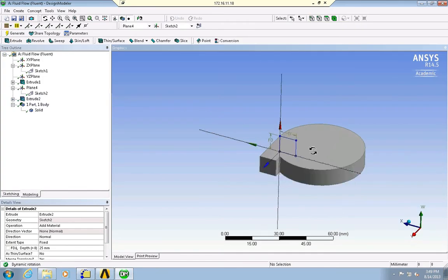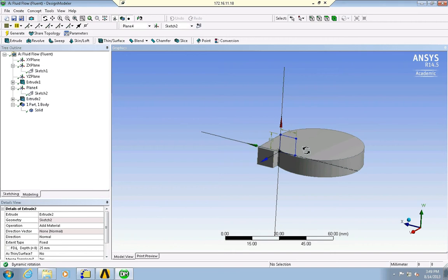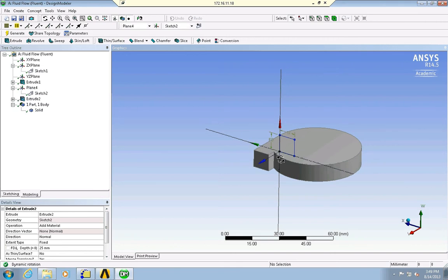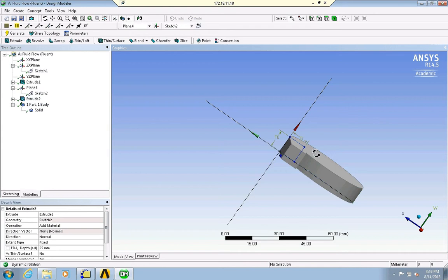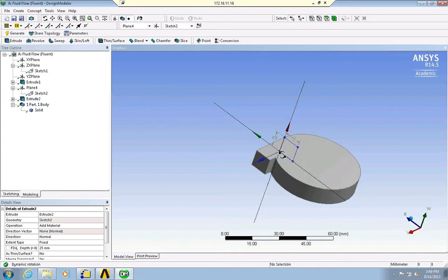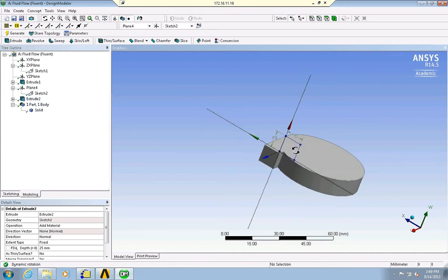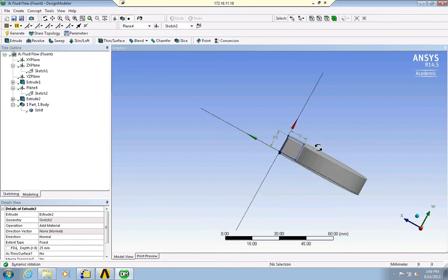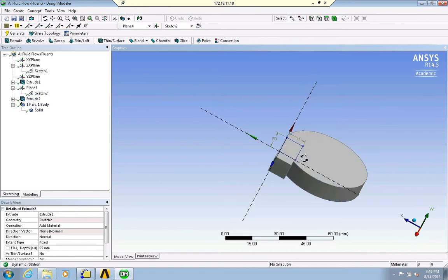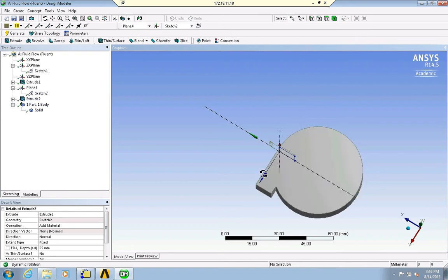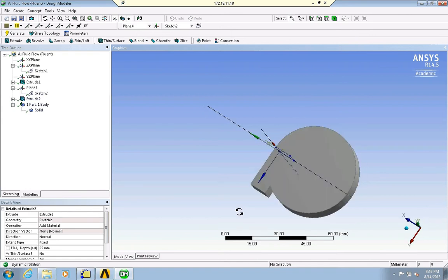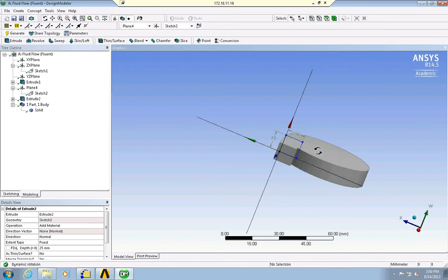Okay, so picking up from where we left off, we've got this square outlet here, and the square outlet is not that ideal. We'd rather have a circular outlet. So how can we actually fix that? Well, what we're going to do is draw a circle that is about a centimeter out here. This is 25 millimeters, so it's going to be at about 35 millimeters. And we're going to gradually transition from the square to a circle.